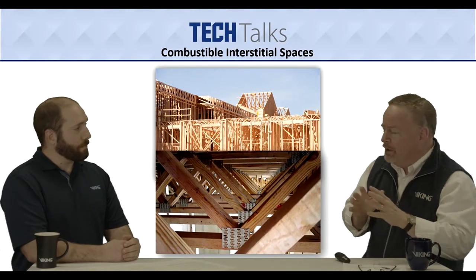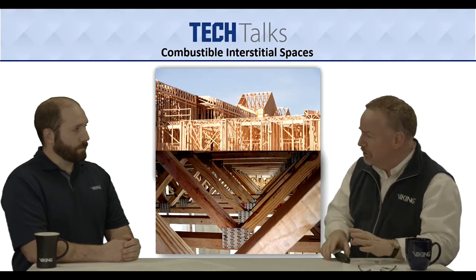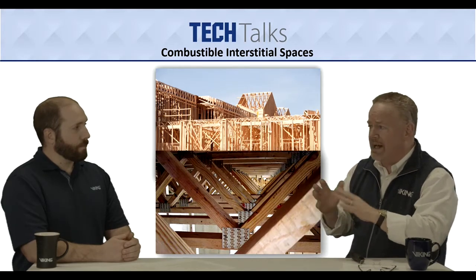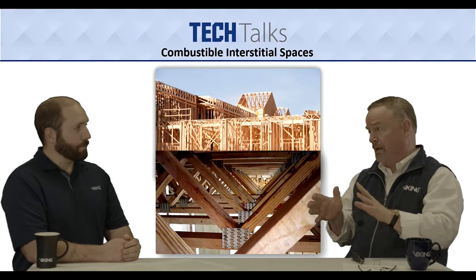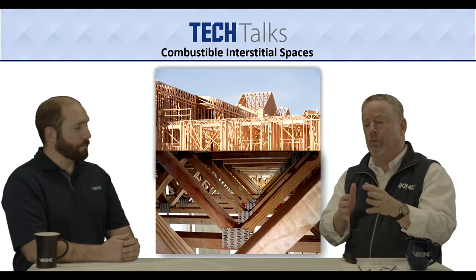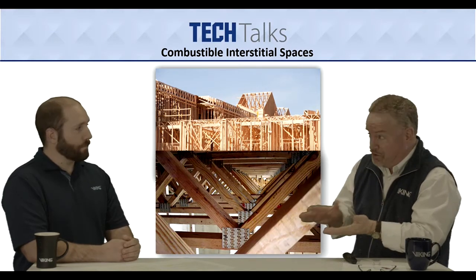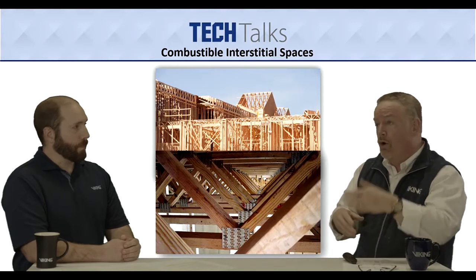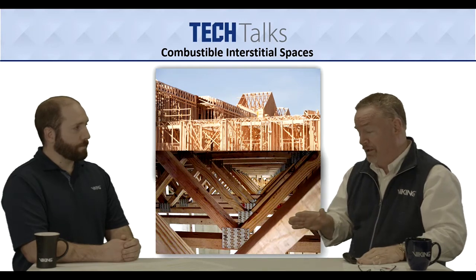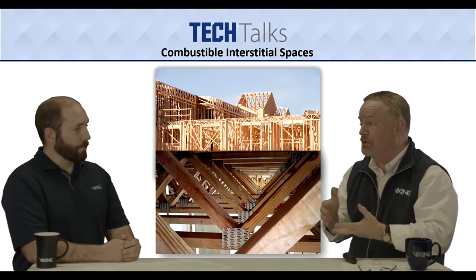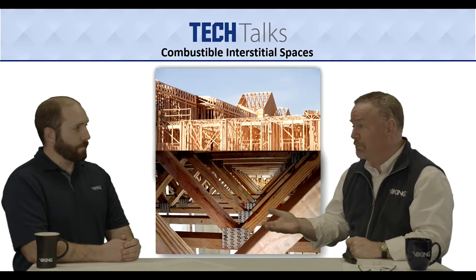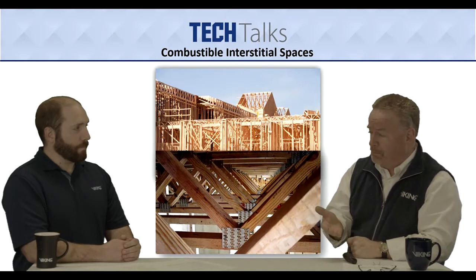So we know now that there's a lot of combustible construction going on in the U.S., and it's peculiar actually to the U.S. and Canada. A lot of places outside the U.S. and Canada don't use a lot of lumber in there, not the way we do in our construction. As a result, we wind up with void spaces or combustible interstitial spaces between our ceilings and floors, or even above in the attic space, where there's a lot of wood involved in very small spaces. And NFPA 13 basically says, if you're sprinklering a building, you're also sprinklering combustible concealed spaces.